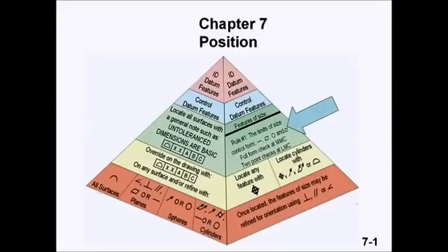The size and form of these features is controlled by the limits of size in accordance with rule number 1. If the feature of size is a cylinder and is coaxial to a datum axis, we will see in the next chapter that there are several ways to control the location. This chapter shows how to locate these features of size using the position tolerance.